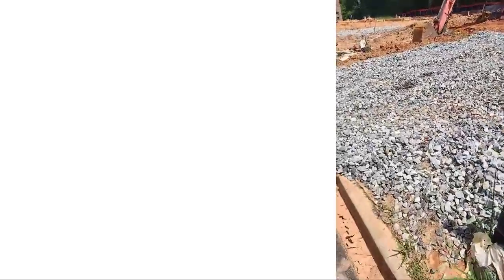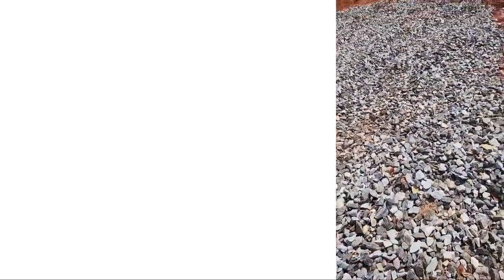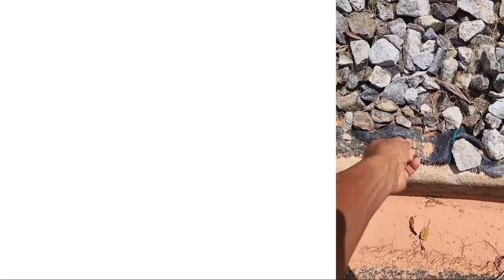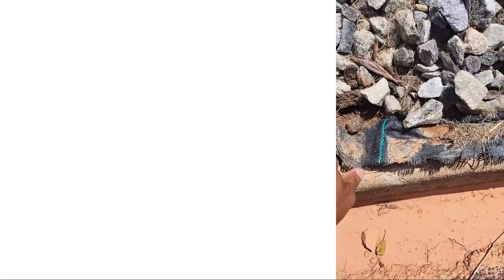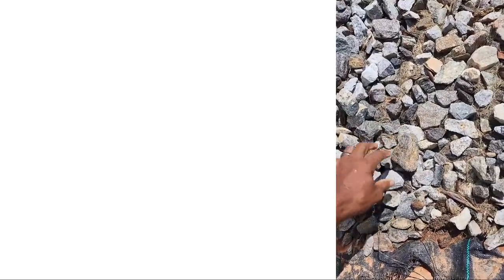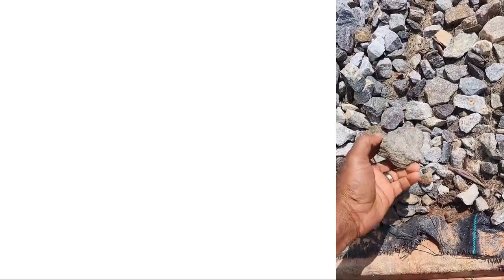Now the next thing that you're going to notice on our site plan is we have a construction entrance. We have one here on this lot. We have one there on the other lot. The construction entrance is made up of a fabric. See this fabric? It's almost like the silt fence fabric. This fabric goes down first, and then we pour stone on it. These are number 57 stone.